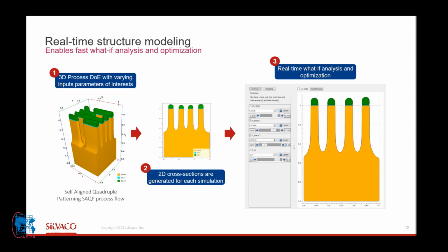For example, if you need a 10 nanometer accuracy, if you do quadruple patterning to get 10 nanometer, that means you have lithography that can handle 40 nanometers. This is one way to do it. To simulate that, we are showing in shallow trench isolation, which is very, very important in a lot of these processes, the ratio of these, the spacing. We can see these knobs getting turned to see how you can optimize. And this does it real time without having you to run a wafer.